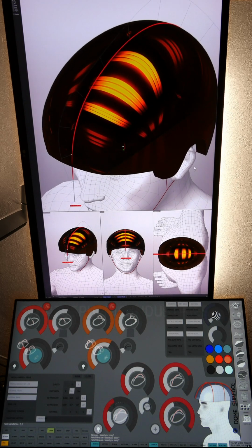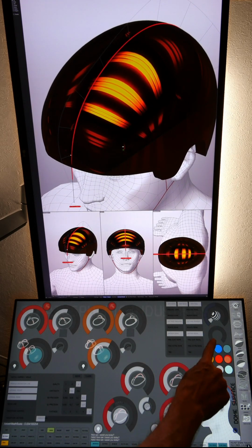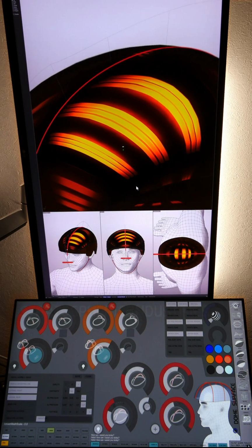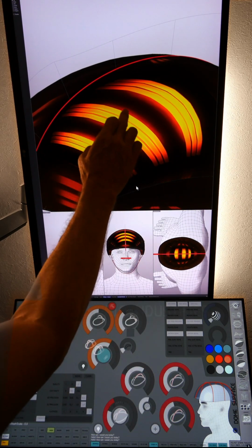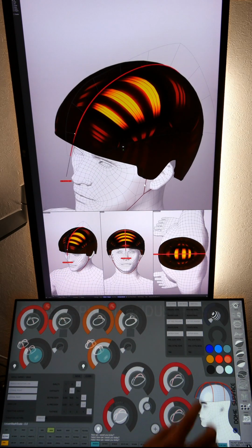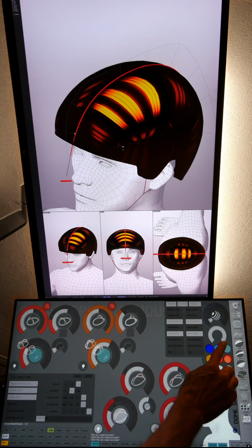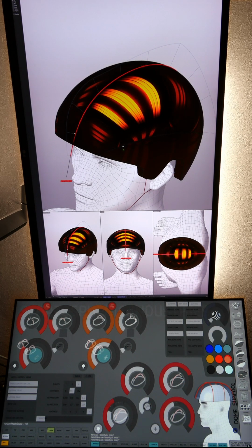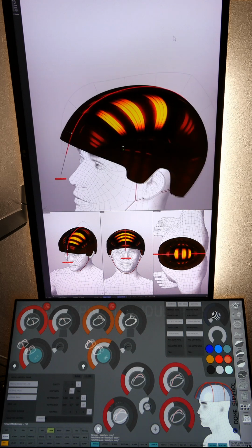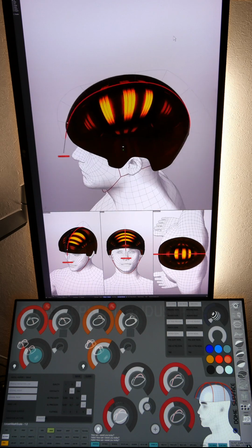Sometimes, if the mesh settings are really low, you can see some roughness in the surface. I'm going to crank down. This right here controls the mesh settings in Rhino. Go up here, check it. You can see a little bit of faceting in the curves, and that makes analysis a little bit difficult. So this allows you to crank up for a little bit at the cost of speed. Crank up the definition of the mesh, and it gets very, very finely meshed, so you can see the aspects.